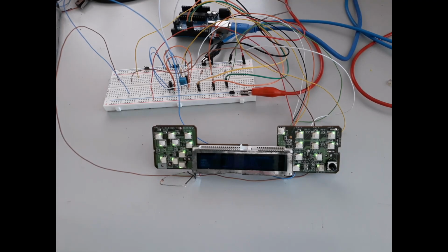The control pins are the usual ones, namely data in, clock, chip enable, and INH. The power is obtained from the vehicle wires with a plus 12 volts DC, and the panel has a resistor and a zener responsible for supplying the logic voltage of 5 volts DC to the driver.